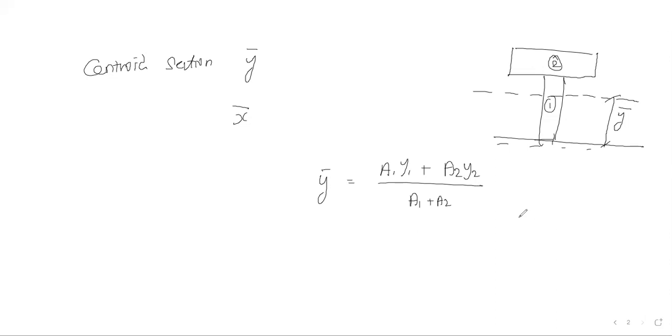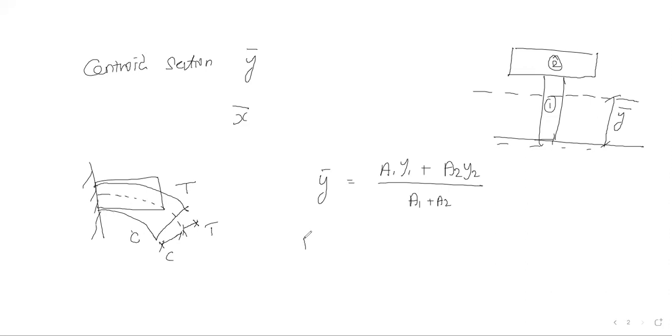So based on the nature, if it is a cantilever beam, it is going to deflect like this. In the top fiber we can have tension and in the bottom fiber we can have compression. So based on which stresses we have to calculate, we find the neutral axis. Whatever the height above the neutral axis, if I use it, it will give tension stress. If I use the height below the neutral axis, it will give the compression stress. We have the formula M by I equals sigma by Y. Whether I use the top fiber value or bottom fiber value, based on that I can get the tensile stress or compression stress.